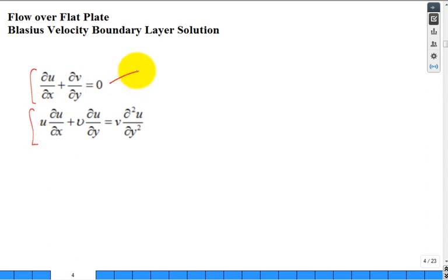They represent the conservation of mass, also called the continuity equation, and the momentum equation. Basically, it's the x direction momentum equation, only one direction of it. The momentum equation is a vector equation in general. And you can say that this is sum of the mass equal to 0. This equation would be F equals ma. F equal ma? Really? Yeah, that's it. In fluid mechanics, that's what F equal ma looks like.